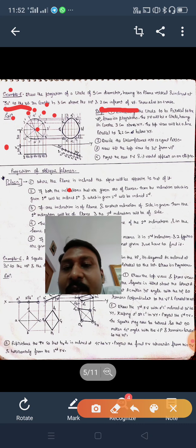Now this plane is horizontal, but you have to incline this plane. How much inclination? 30 degrees to VP. So slightly away from this figure, make one point here, and from this point take a 30 degree angle, mark anywhere 1 dash. Then from point 1 measure 2, 3, all this distance and cut the arc here. Then you will get this plane here.